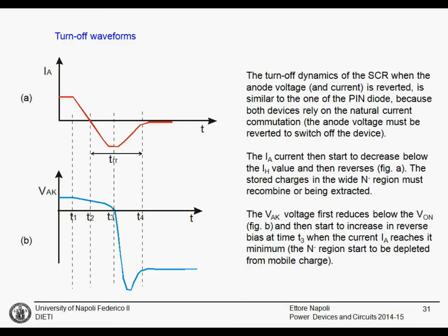You can also see that there is an overshoot. This overshoot is usually caused by parasitic inductances. Without parasitic elements, this voltage should go up to this value. This is the bus value, negative bus value, but without the overshoot. This concludes our study of the classical thyristor.